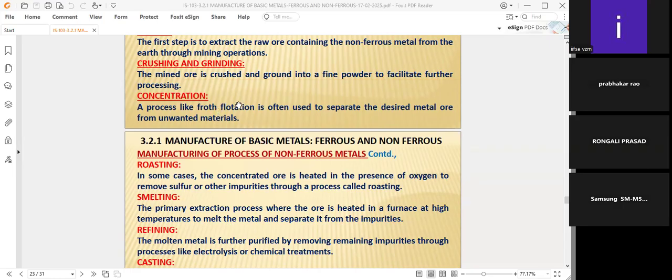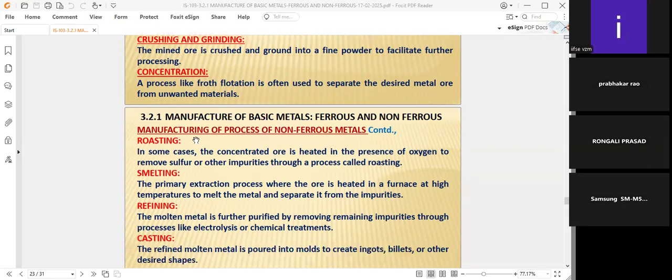This is one method to select depending upon the non-ferrous material, depending upon the ore. Next, suppose flotation is not encouraging, where sulfide ore is there, in which the sulfur content is more, and the non-ferrous metal is there. During the lab study, we can diagnose what kind of impurities are in the ore.